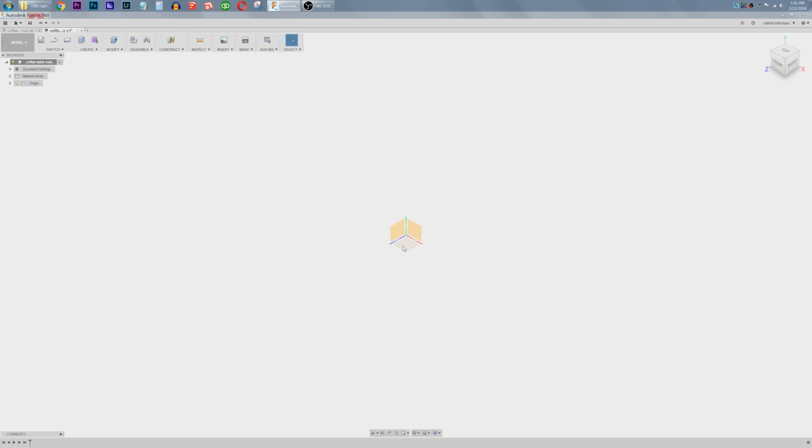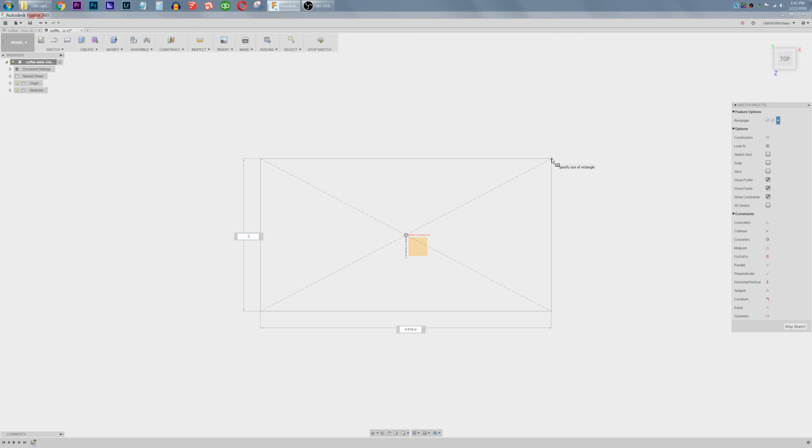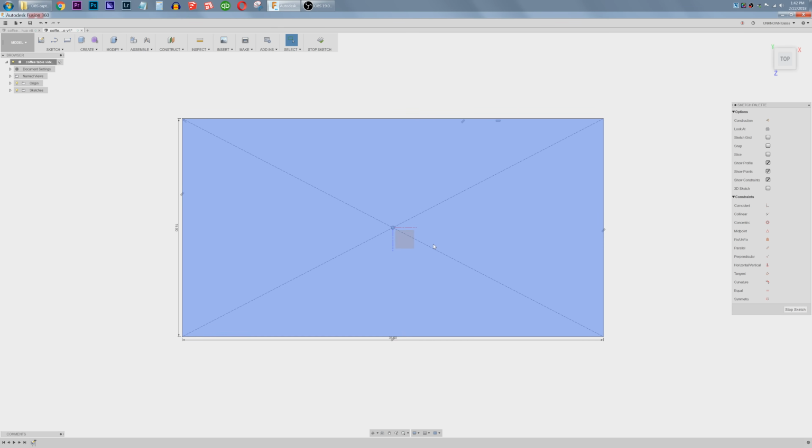I do something similar in this, but not quite 3 dimensions just yet. I always create a footprint sketch on the bottom plane, which in this case is the blue-red plane. So right off the bat, I'll select this plane, which is the bottom, and go to 6 o'clock to create a new sketch. R for rectangle, and we'll use a center rectangle. I always make my footprint centered on the bottom plane on the origin. And I'll click and drag in this direction. I'll say 19 is my first dimension, which is my width, and tab 36, enter. Let's zoom out.